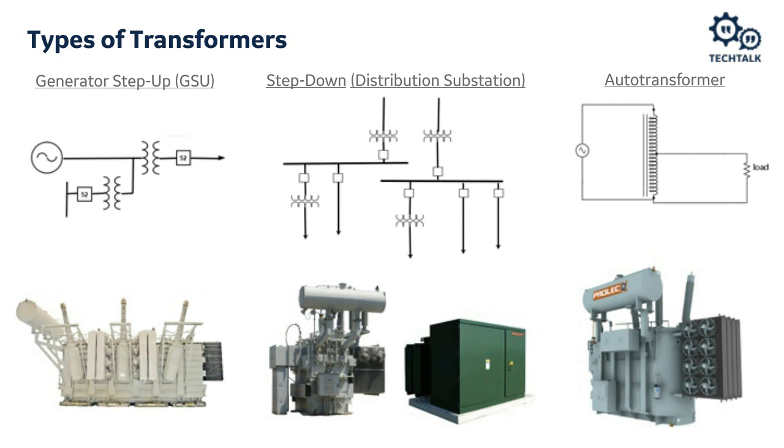There's several different types of power transformers that we need to protect. The largest transformers you'll see are generator step-up transformers on the left here. Typically, when we say a GSU, we're referring to the enormous transformers you'd find in power plants or other points of generation. The output of large generators are usually at something like 18 kV or so, and we use the GSU to increase the voltage up to a transmission level voltage, say 69, 115, 230 kV, or whatever it may be. Because of the sheer size of these, redundancy is uncommon.